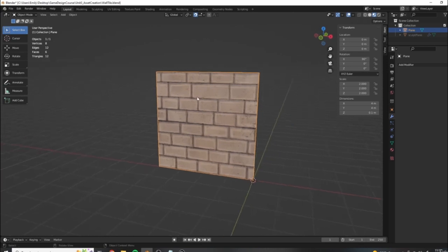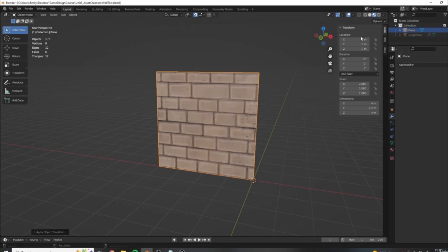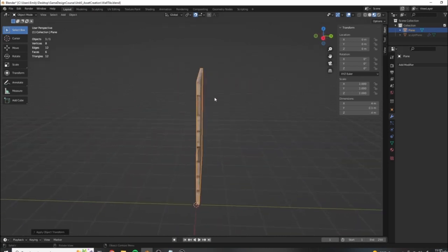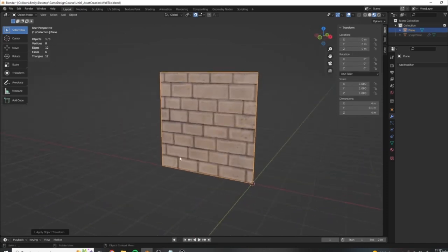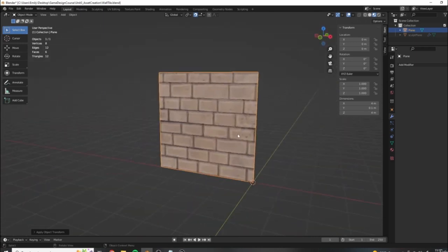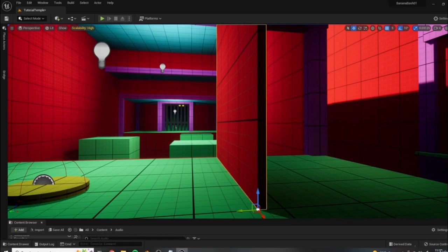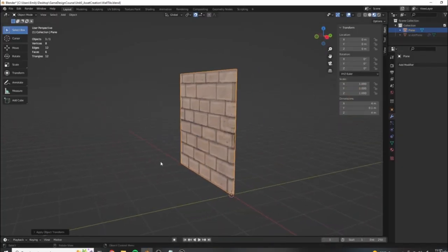So I'm going to select my mesh in the 3D viewport. I'm going to hit Control and A to bring up the Apply menu, and I'm just going to hit All Transforms. So nothing has changed about our mesh, but all these numbers have been zeroed out. So we're basically saying this is the basic dimension for this mesh. If you remember, this is analogous to baking our rotation and scale when we were generating our prototype meshes. So that is essentially just what we have done here.